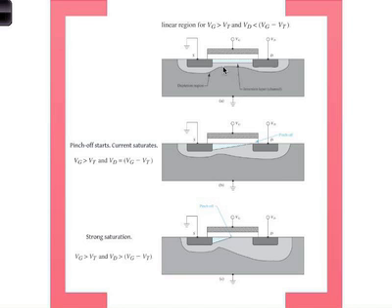If you look at this region right here, this is a P-type region, lightly doped P-type region. When you apply a positive voltage on the gate, you attract negative charge. You induce a negative charge on the other side of the insulator.